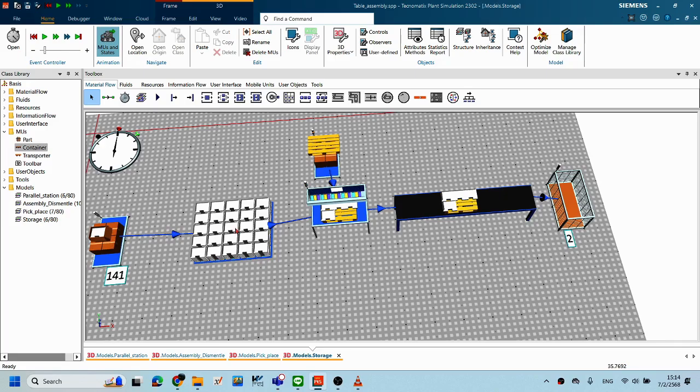Right now, the feed fills into the storage one time for four parts, because the storage is being pulled out to the SMB, and the SMB takes one main part and four sub parts, attached together and sent to the output already. It's not necessary to feed four at one time, it can be one by one. How will it be set? This is the idea. It's flexible.